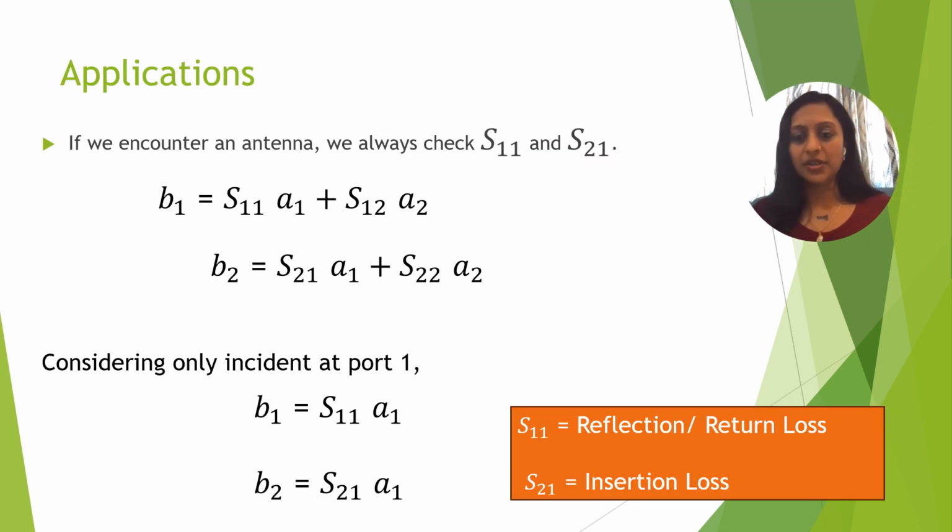Where do I use this? What's the application of S parameters? As simple as if we consider an antenna, many times we check S11. If you simulate an antenna and want to find out its first performance, it would be the impedance matching. So I measure that with S11.